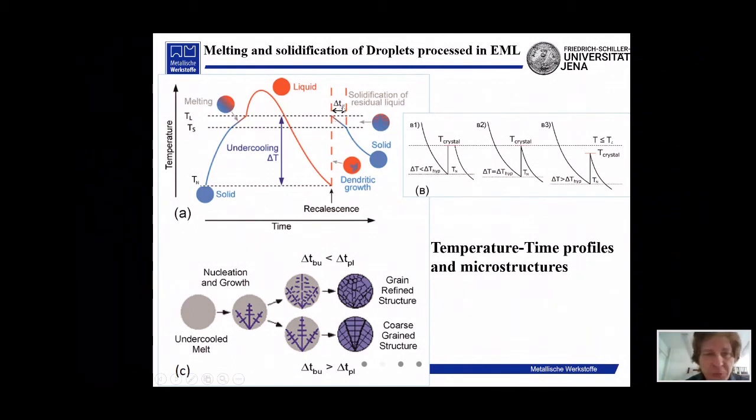Which types of plateau duration? This is delta T plateau, delta T PL, the time duration at the plateau. Which types of plateau do we have? So, the classical type: we cool down to some nucleation temperature with an undercooling smaller than the hypercooling limit. Then we can start recalescence and come to this crystal temperature, which is slightly below the liquidus temperature. Then we can stay at this plateau and cool down again.